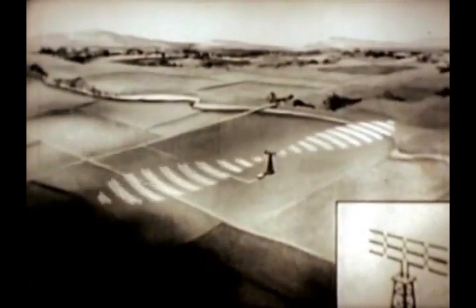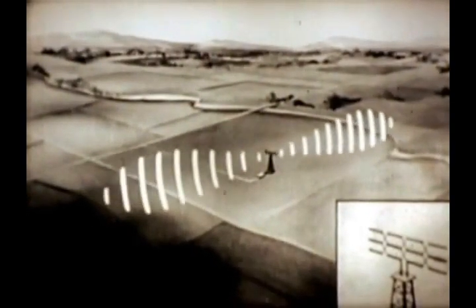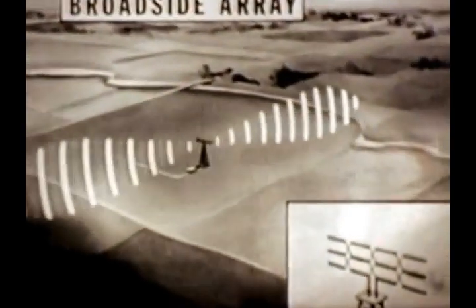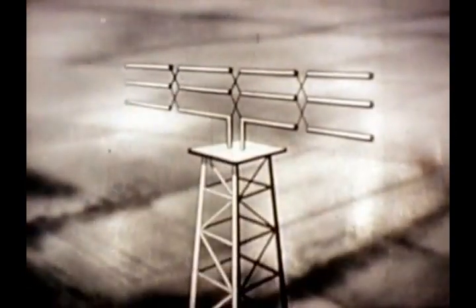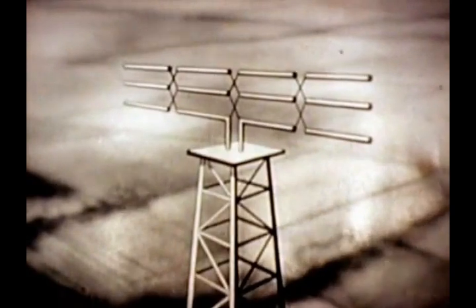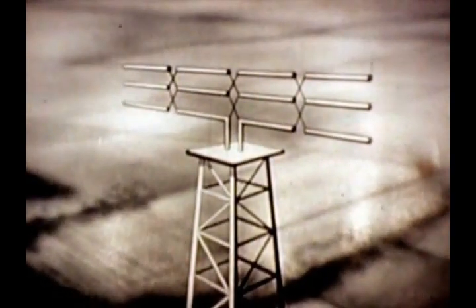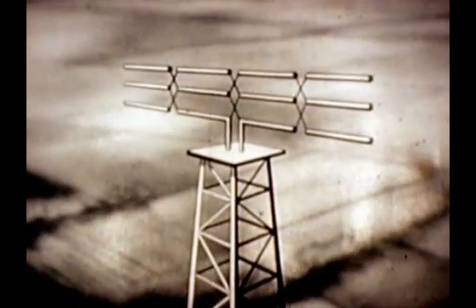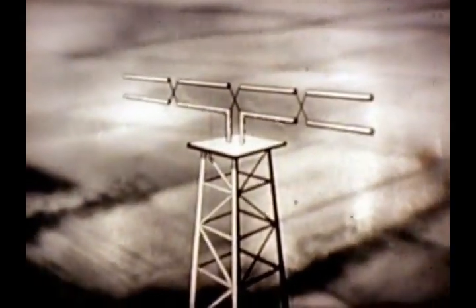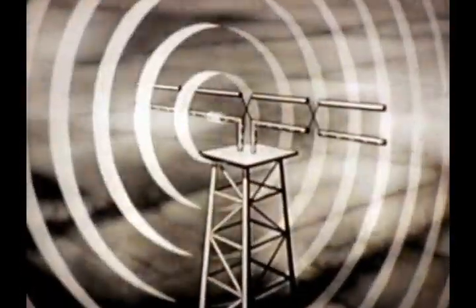When, in addition to horizontal control, vertical directivity is necessary, another antenna, the broadside array, can be used. Like the collinear array, the broadside array is generally stationary. The array is made up of many half-wave elements. These elements are formed into several levels, much like the rungs of a ladder. Let's consider only two levels. When energy is fed in phase to the elements of the lower level, the result is, of course, a collinear pattern. And now, let's energize the upper level of elements.